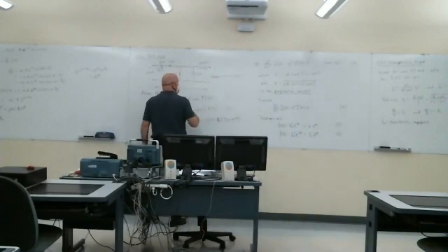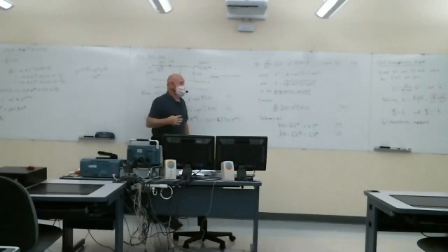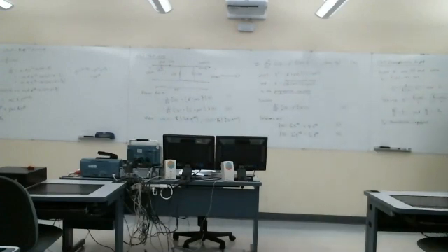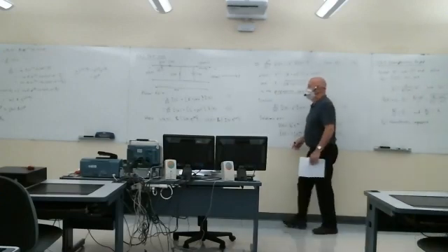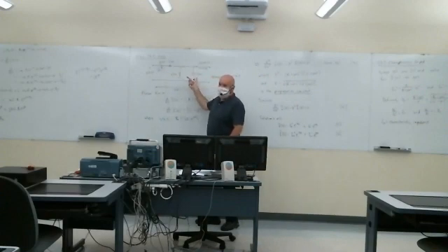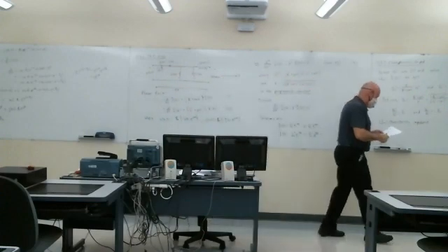Here, the impedance of a capacitor is 1 over j omega C, right? So to get that infinite impedance, 1 over j omega C, we want C to be zero as well, to have infinite impedance. Ideally, we'd like these two elements to be short circuits, and we'd like these two elements to be open circuits so that there's no conductive path between the two wires.